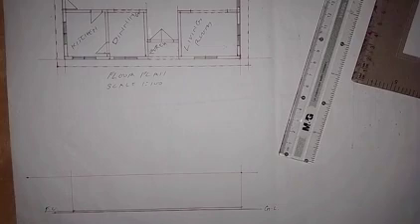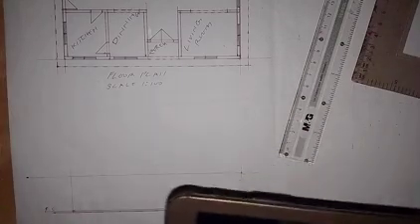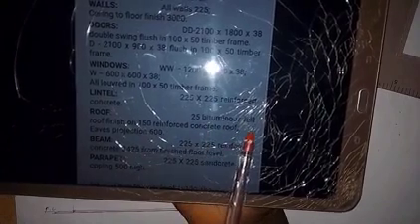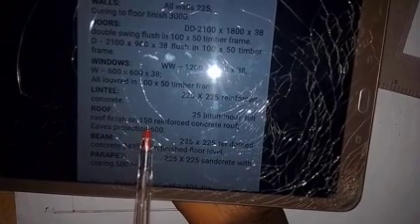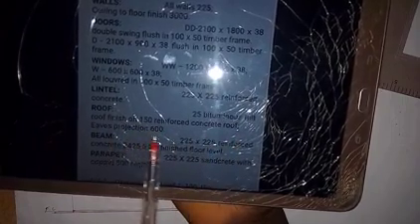Now let's work on the roof. The type of roof given to us in this drawing is a flat roof or parapet roof. Coming to the roof here, we have 25 bitumen felt, then roof finish on 150 reinforced concrete roof, and this projection is 600.